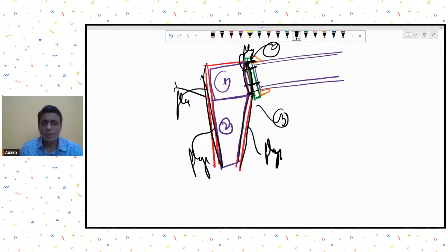And plus at this joint, you can provide a full penetration butt weld, or you can just provide a half penetration butt welding, or some people will add an extra plate over here at the underside and provide a fillet welding. Whatever you want to do, it's possible to do. Okay, understand, but column flange is not required to be bent.